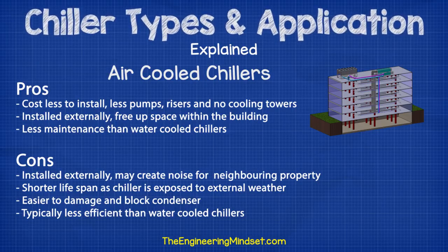Air-cooled chillers require less maintenance compared to water-cooled chillers, again because they have less equipment. Air-cooled chiller systems are much simpler and easier to design and do not need another set of pumps for the condenser loop. Some of the cons for using air-cooled chillers is that air-cooled chillers sit outside the building. Their fans and compressors will create noise which the surrounding areas might be able to hear, although some measures can obviously be implemented to reduce this.